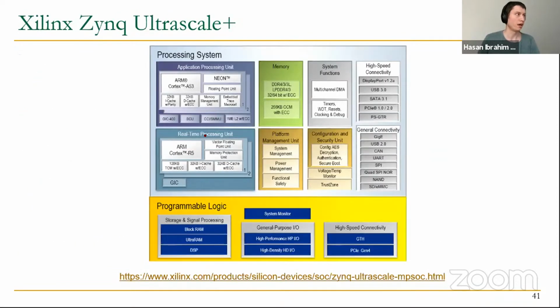And this is one example of such an FPGA. This is the Xilinx Zynq UltraScale+ FPGA. And you can see that it implements various blocks. It implements a memory controller to access DRAM. It implements some high-speed interfaces such as USB, DisplayPort, HDMI, PCI, and other things. It even includes special blocks to do data encryption and decryption. And here you can see 2 processor cores are also inside the FPGA.